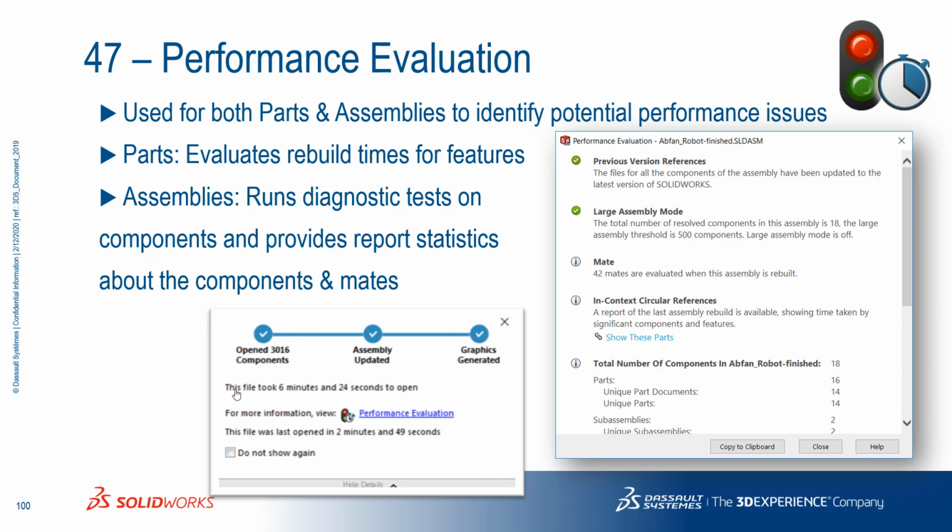Performance evaluation, definitely recommend taking a look at this. This is a good way to understand if you're having performance issues with your model and where that might be. If performance is something that's important to you, you're running into performance issues, it's slowing you down, here's the first place you should go to look to see what could be causing that. So it's a good way to understand the root cause of performance issues if you're having them, all right? You can start to see rebuild times. So say, for example, something takes a long time to rebuild, that would be the first place I would look to understand the implications it has on the performance of your model.